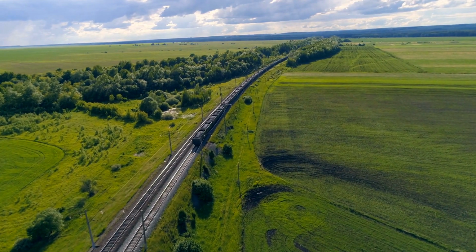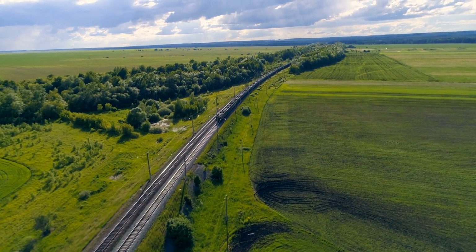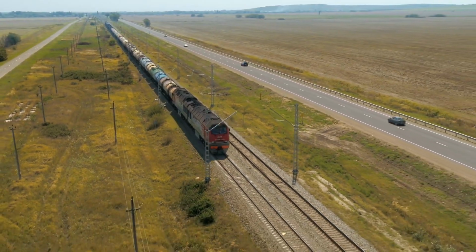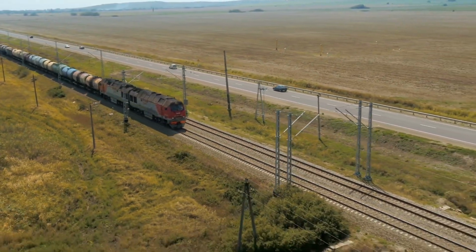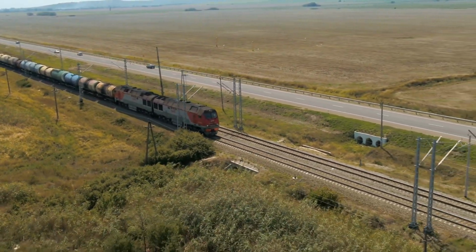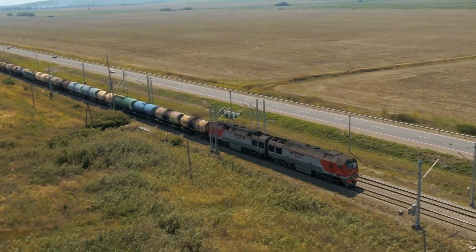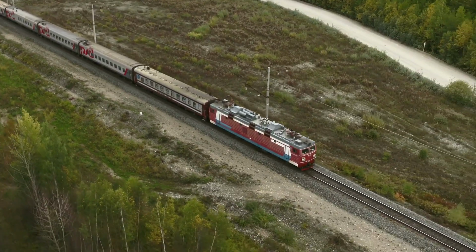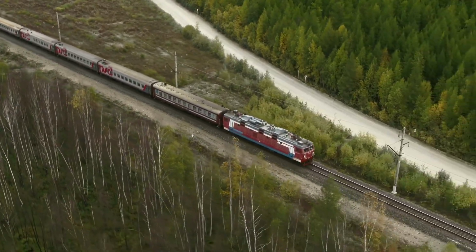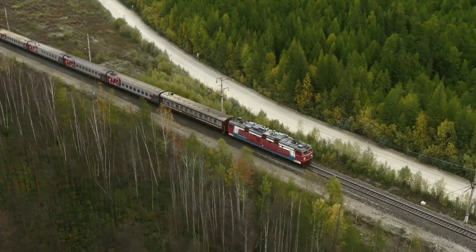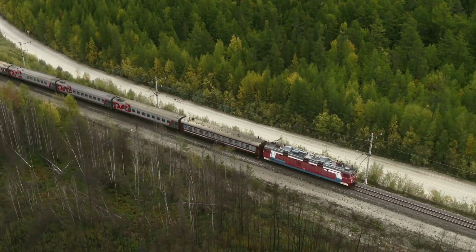The desire to increase the number of trains running, decrease the time staff spend on track, increase efficiency and accuracy are just some of the factors driving a change in the way inspections are undertaken, especially the most basic inspections. In the UK, BVI has been replaced in part by the plain line pattern recognition train. This uses high-speed cameras and machine learning to spot faults and issues with plain line. Commonly mounted on the same train that records track geometry, it removes the need for staff to walk long sections of plain line.